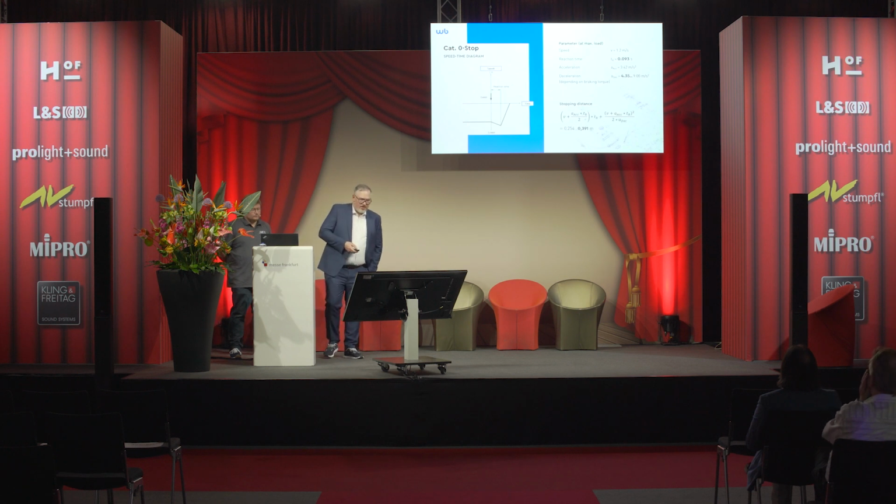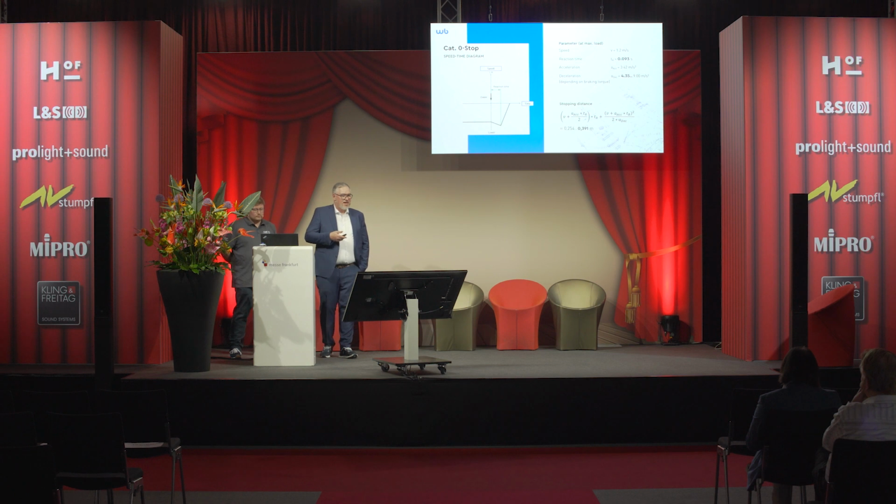So if we calculate the resulting deceleration rates at max load, we always have to do this at max load and min load. You see that there is an effect. If the category stop event is happening, there's a reaction time. In this time, there's no torque on the motor, and the machine starts decelerating. And the deceleration is not fully with gravity, because there's, of course, the inertia mass of the motor that needs to be taken into account. But you see that you still have a certain reaction time.